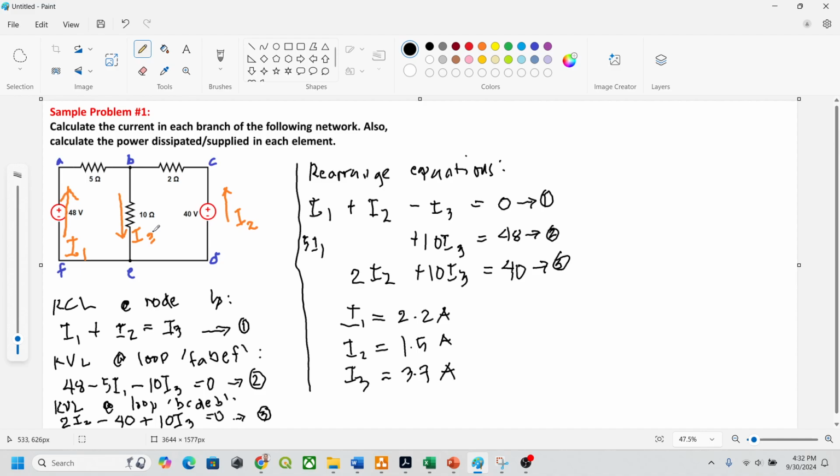Okay, so basically if you are asked to solve for power, for example, the energy a particular load or a particular resistor is consuming, you'll start with solving your branch current. Okay, so this is how we do analysis with networks composed of one or more power supplies.